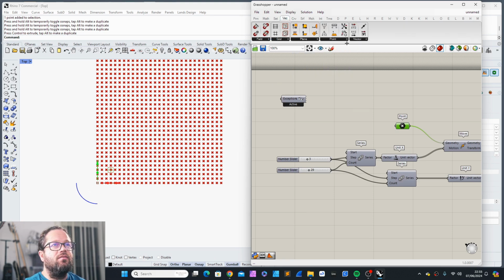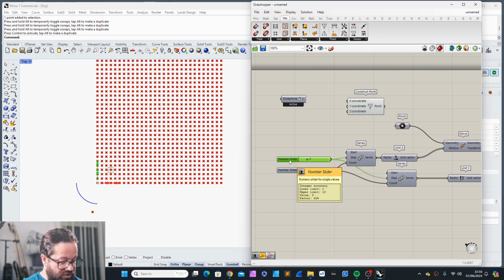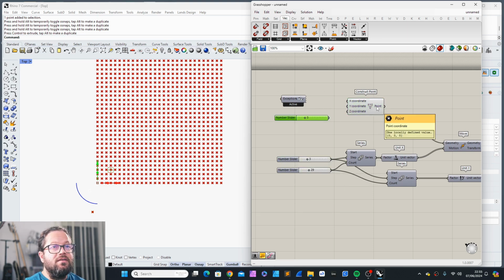For that, we could create this point here. It's called vector construct point. And if I use this tool, actually there's already a coordinate in there. So I could use again X, Y, and Z coordinates. In that case, these would be just simple sliders. And the output is a vector. In that case, it's 0, 0, 0. That could be going here.